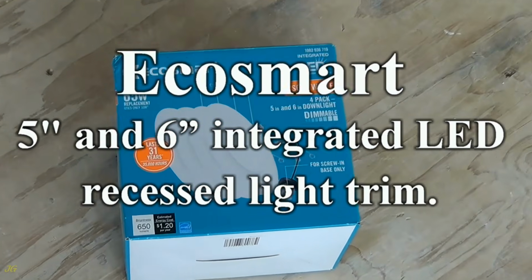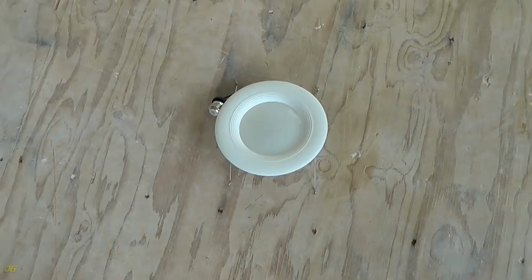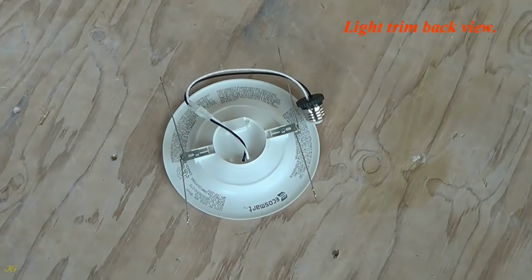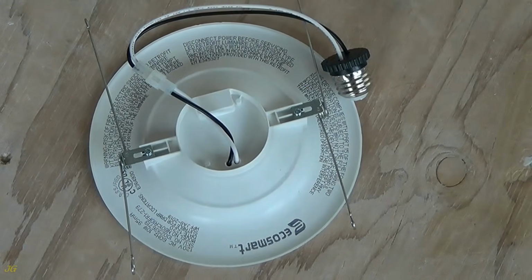EcoSmart 5 and 6 inch integrated LED recessed light trim. Light trim front view. Light trim back view. For a 5-inch housing, loosen the screws on the torsion spring brackets. Slide the brackets toward the center of the trim and retighten the screws.